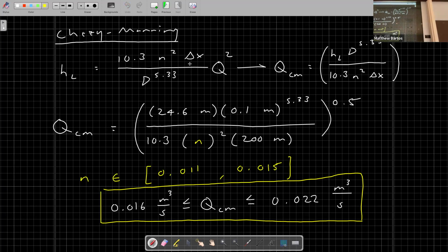So like I mentioned before, usually the roughness parameters are the largest source of uncertainty. They contribute more uncertainty than the selection of the equation itself. So basically, in most cases, it doesn't really matter which equation you use as long as you nail down those roughness parameters accurately.